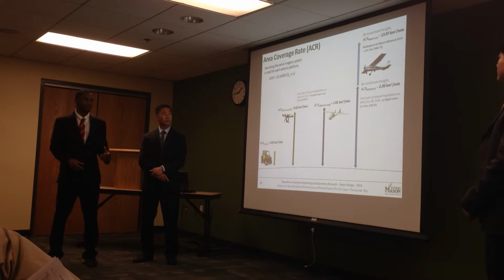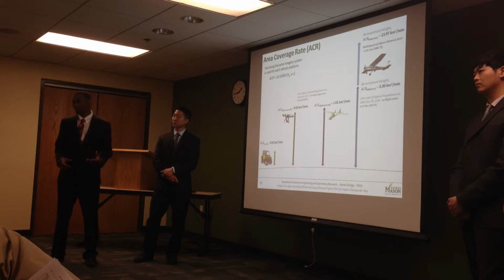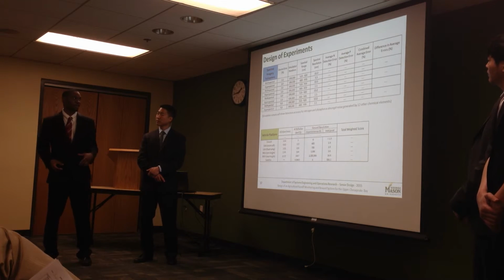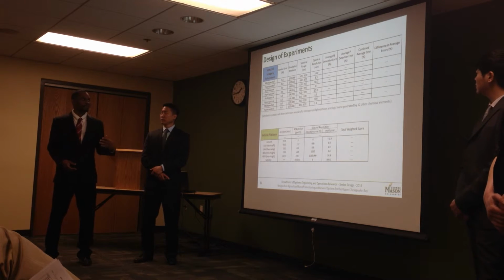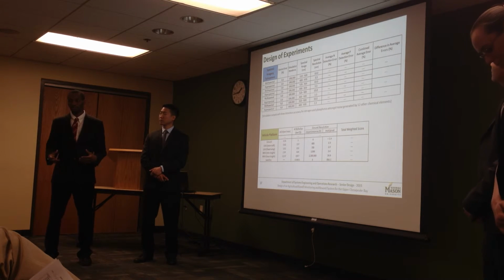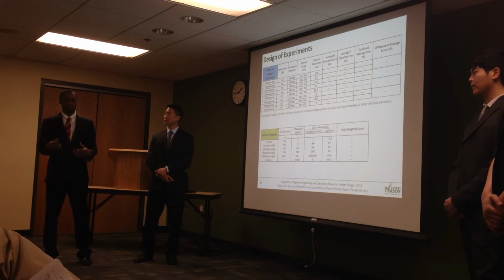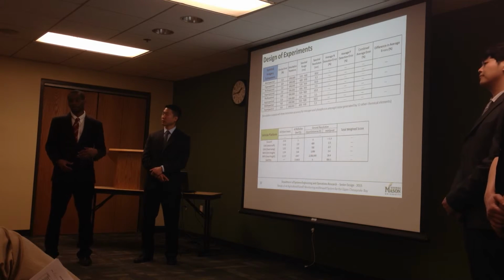Also, we evaluated the manned aerial vehicles at 2 different levels. One is at 500 feet due to FAA regulations, and the other is at 3,000 feet due to limitations with the multispectral system. And while running our experiment, we set our device error between 1 and 9% to be able to take a look at the average nitrogen and phosphorus detection error rates between the multispectral and hyperspectral system. This will give us an opportunity to compare and see the differences between the multispectral and hyperspectral systems. With the vehicle platform, we were able to get the ground resolutions from the manufacturers.